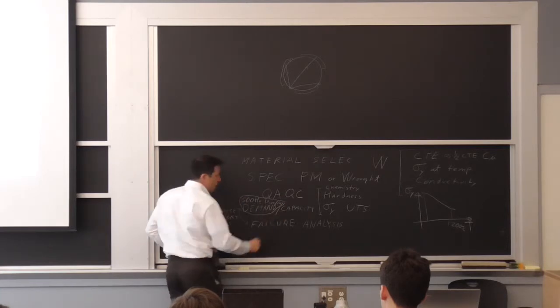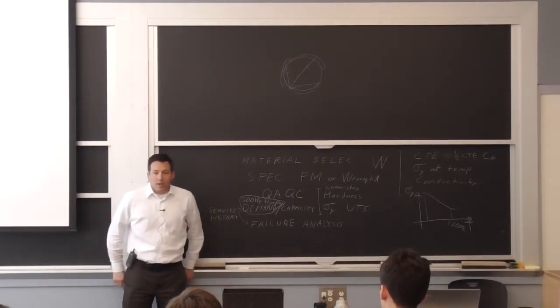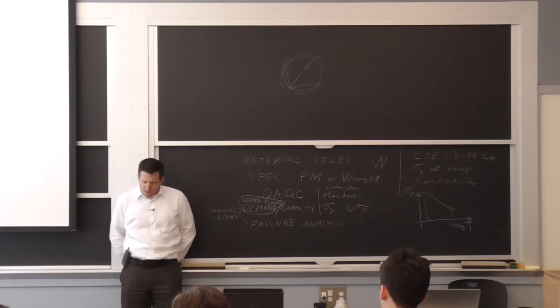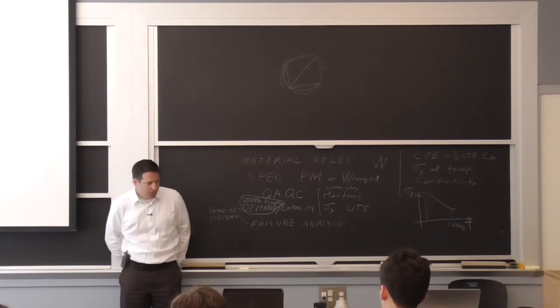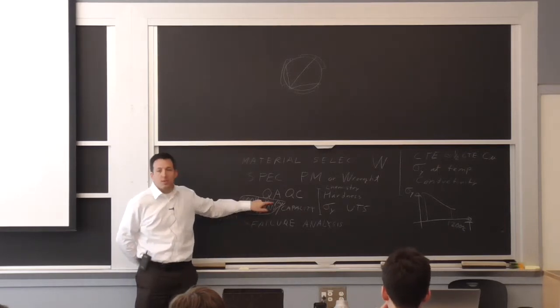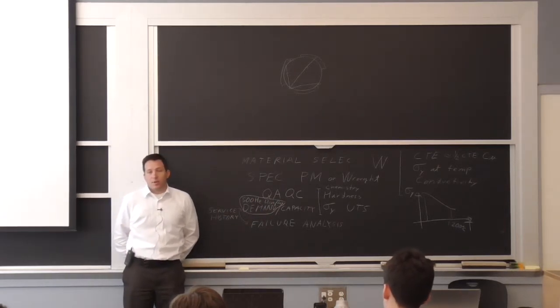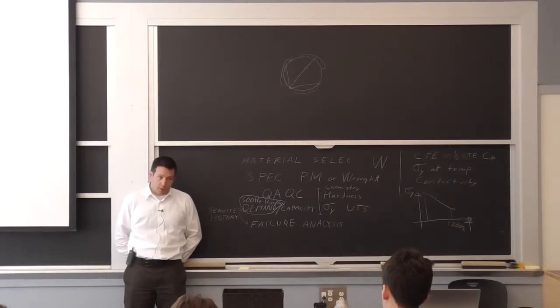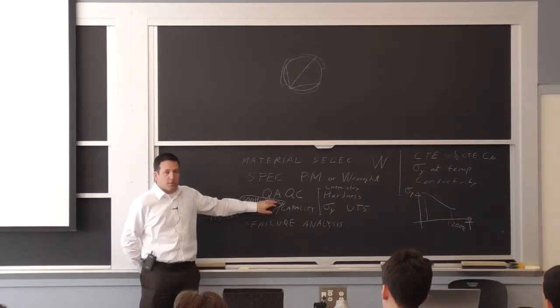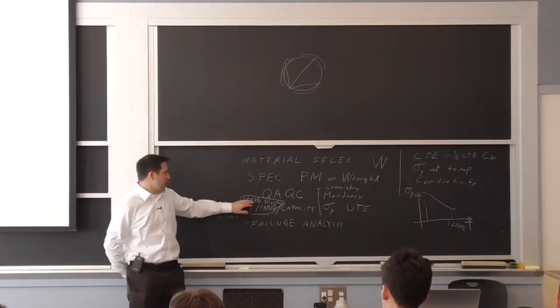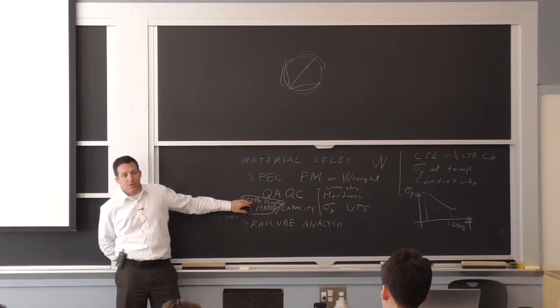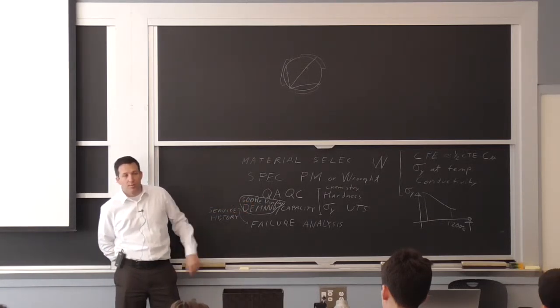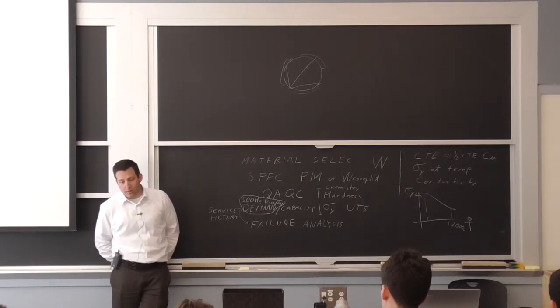But these are much bigger. It turns out, under some conditions, we had a good indication that these were the ones initiating the cracks, the big cycle. But if the problem didn't show up before, it's because if you had a small crack at 12 cycles per day, it wouldn't grow very quickly. But if you can initiate a crack with the high stress cycles, and then continue to grow the crack under these smaller cycles from turning the current on and off, that is really the reason why they had a lot of failures.